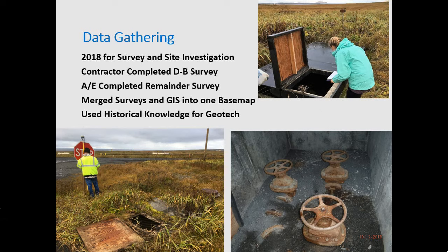But then there's other places where the valves were direct buried, which is what my experience is more standard. So to have all of our valves and PRVs in a vault, but all of our valves and bends and flanges, they all wanted them in vaults. And we worked with the owner early to talk through what that was going to look like in the end if you wanted to put those back in, because that was going to be pricey.